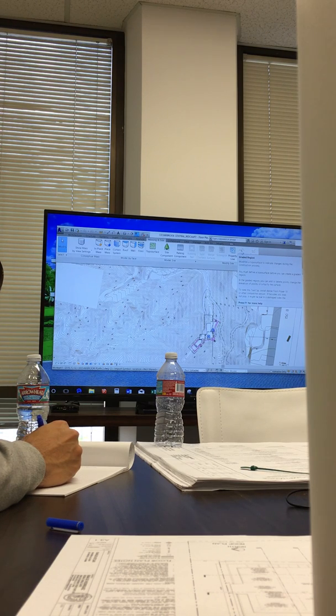So in terms of the grading plan, when you would get it back from the civil engineer, you would want to offset it as well, right? That way Revit can see it in 3D to be able to generate that. If you get it back from the civil engineer and it isn't in 3D, you would need to make sure from AutoCAD that it is, that your z-axis is reading properly. Then the coordinate you used originally would be the same coordinate, correct? Yes.